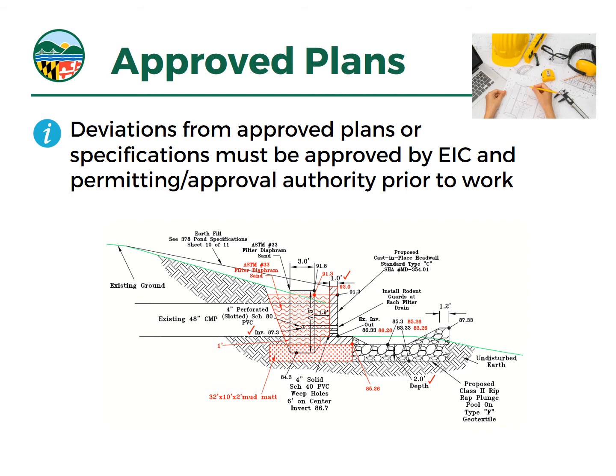Now, it's not to say those changes were necessarily wrong, but what they didn't do is maybe consider some of the other bigger picture impacts of those changes. The dam eventually developed a seepage and piping internal erosion problem, and like I said, failed on first filling. I believe it killed about 14 people and had billions of dollars of losses. So we want to avoid that if at all possible.